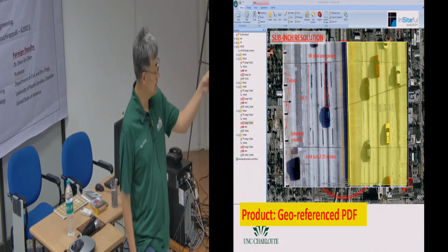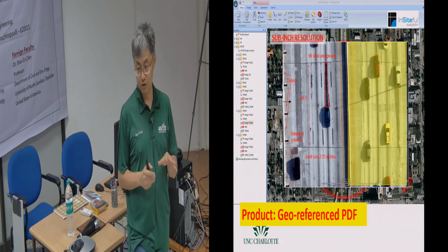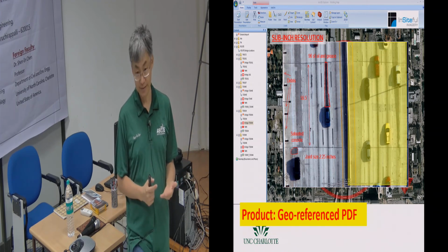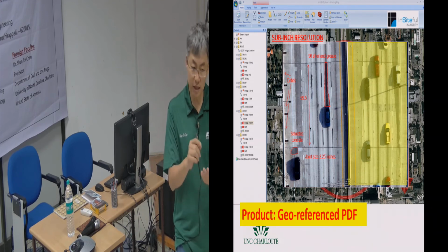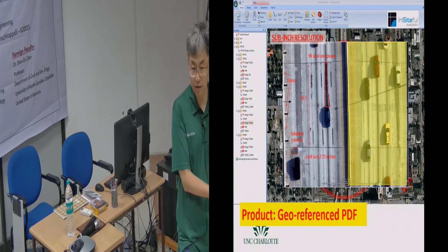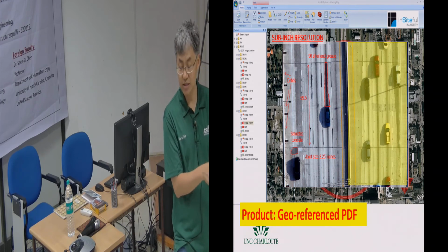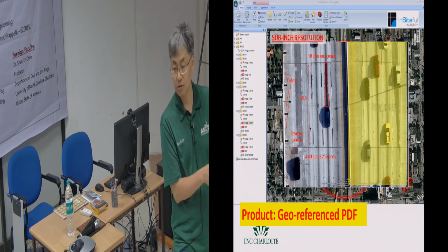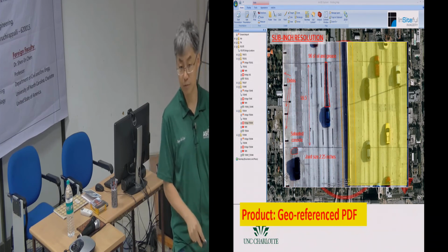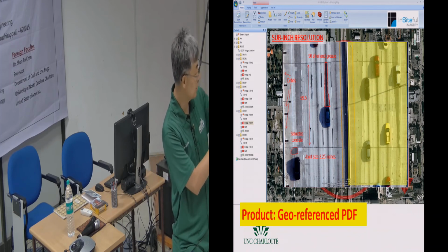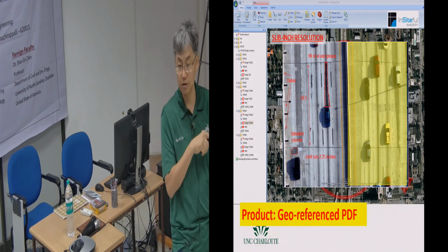But anyway, another really cool technology is that we have those pictures, and those pictures are GIS georeferenced when they are embedded into a PDF. This is a very important part. When you submit a report to your client, a written document, and they have more questions, they have to come back to you, because it's all either paper or a Word document. But with this technique, if they have ArcGIS, they can open the PDF and do measurements on your pictures in the PDF document. In other words, if you don't believe our analysis, you can do your own analysis and prove that we were right. With all these embedded pictures, the engineer can use the PDF to open up, change the viewpoint, and do any measurements of a particular crack they're interested in.